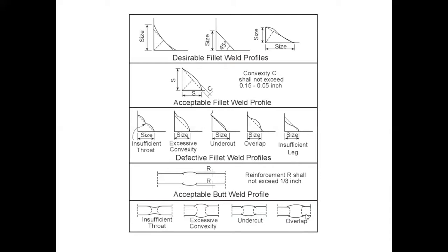I had a student come in the other day in my 30 level, and they had to catch up on a weld. They tried one, and they ended up very, very wide on it. And that would have been an example of overlap. So instead of being a maximum 1/8 from the edge of the weld, because if we're looking at this profile here, you don't want to come more than 1/8 into the plate on either side from the edge of your butt weld. Here, this is much farther than that.